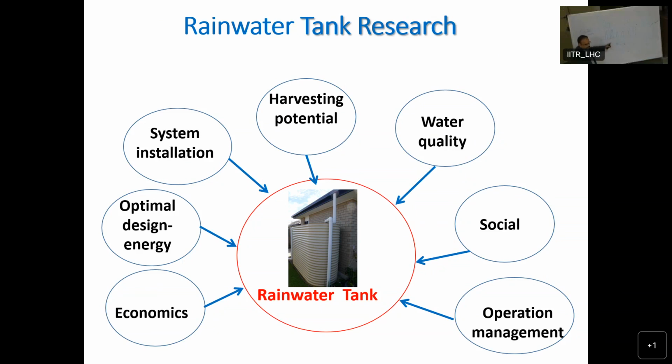And this factor, as we were talking about yesterday, is the number of days where the rainwater is not available. The number of days can be significantly high if the monthly variability of the rainfall is significant. So as I said, if you have 200 days instead of 112 days, then you need a very large size, but the water is not available. So we have to keep in mind, while designing these systems, the actual availability of water. Is it making some sense or clear?